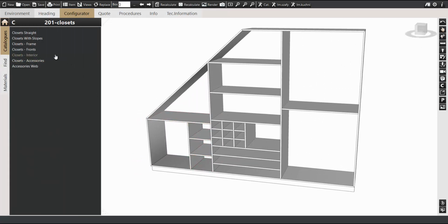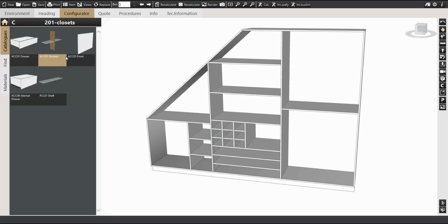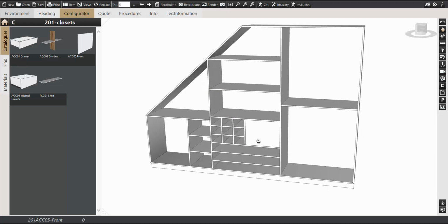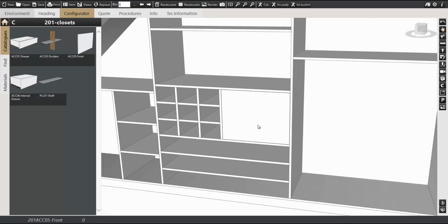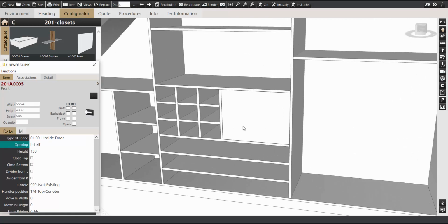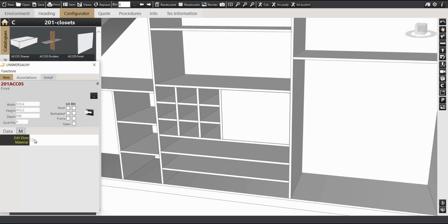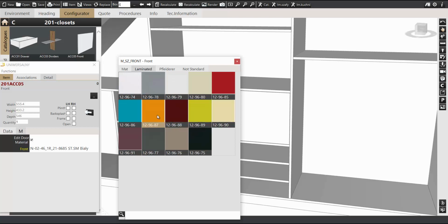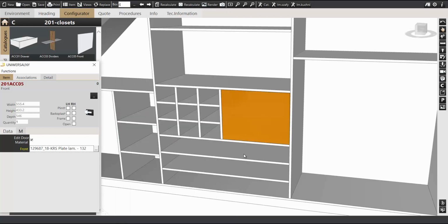So you want to use the door now for the construction. Same easiest way. Just select the door function after the space where you want to place the door, and the door is placed. After this, you can use the opening function to show all the movements in this part. But first we change the material and then we open the door. So we choose in this case an orange one to show you better what has changed.